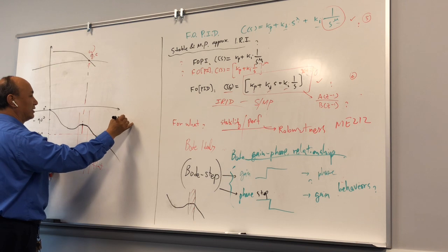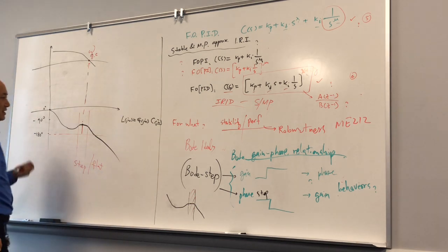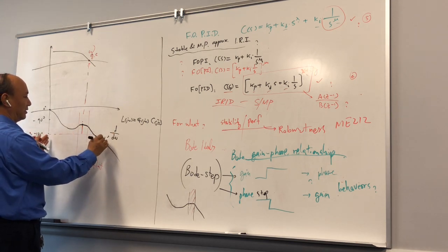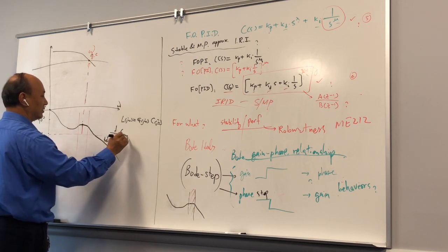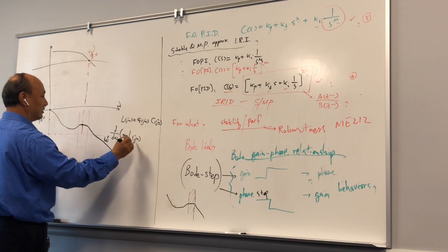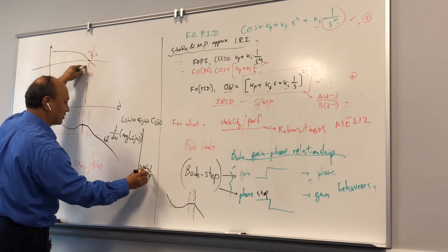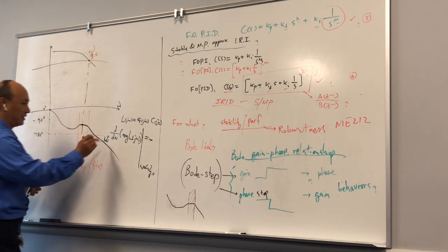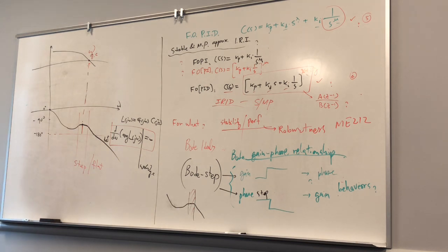So this loop gain is G(jω) times C(jω). So basically here, this is my omega, and this is d/dω of the argument of my L(jω). When omega is omega gain crossover, when this is 0, it means it's flat. So this is called the flat phase condition.